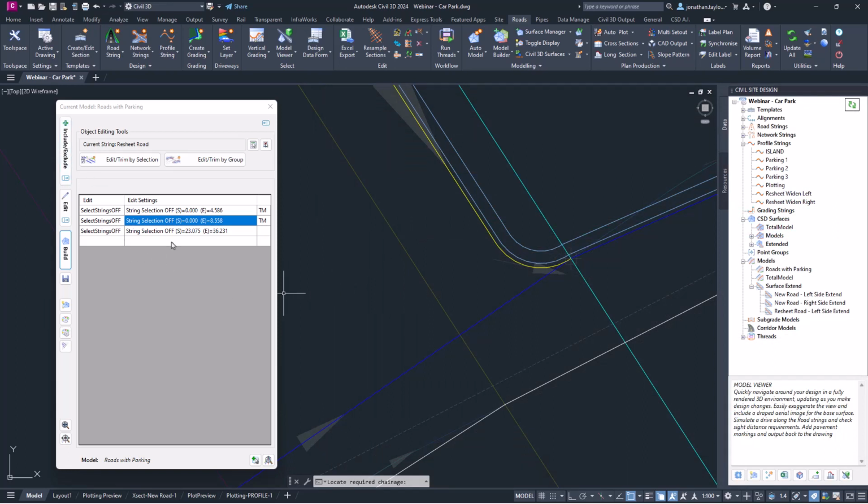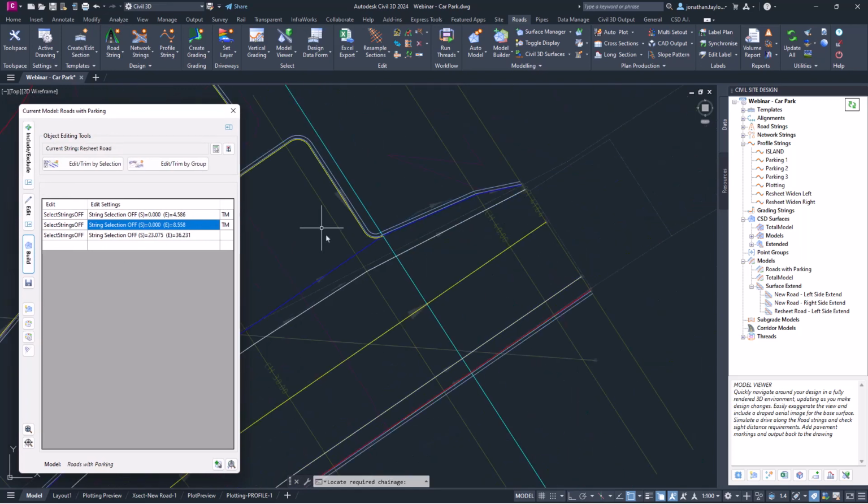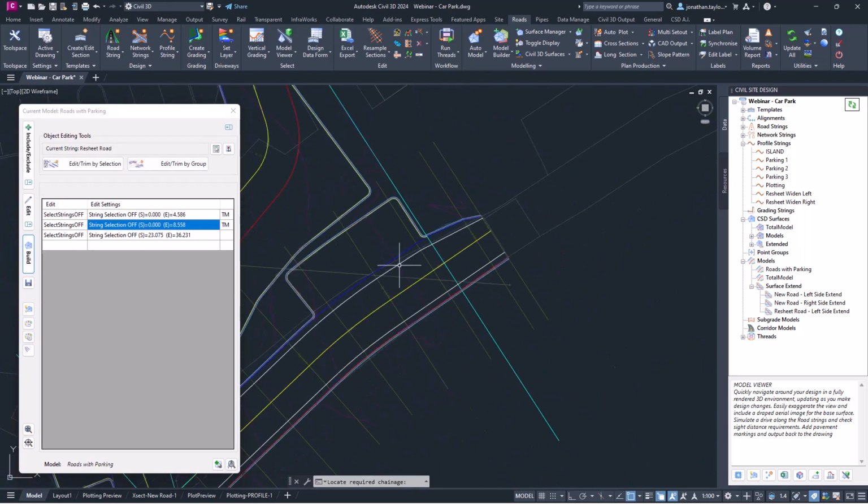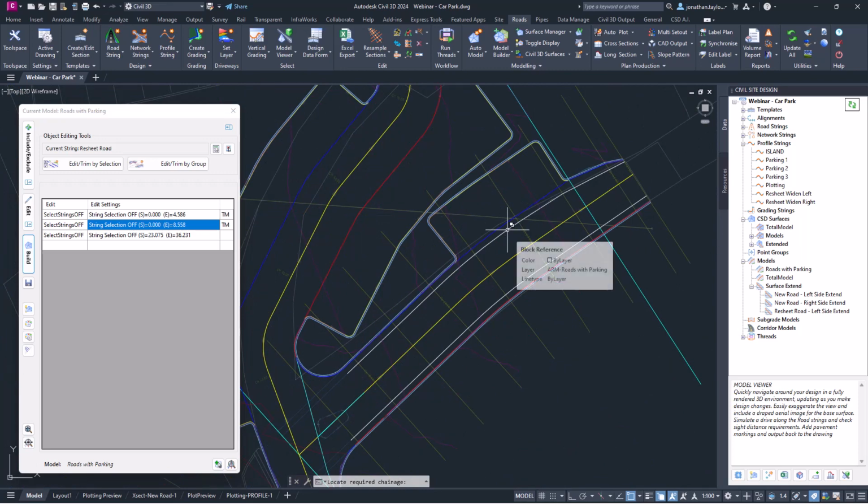Once you're happy with the edits that you've been making, really you've seen the extent of what Model Builder is all about. It's very simple. You're simply connecting strings together, cutting the line work or the codes out that are not appropriate or you don't need, and then simply building. Now there are some scenarios where building could effectively encourage zigzagging or sawtoothing to occur, and there can be reasons as to why this is happening, and normally it's to do with conflicting codes.